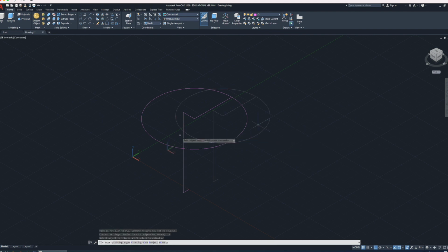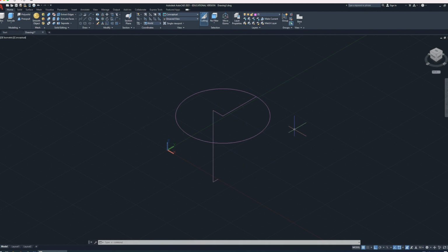the torso. So towards that end, I'm going to get the trim tool, but I've got to specify the part of the circle that I want to trim away. I just want to preserve this, like I said, a quarter of it. So I'm going to get a line tool, go to the right shoulder, and I'm going to just temporarily create a line here that goes out to the side from the right shoulder that intersects the circle.